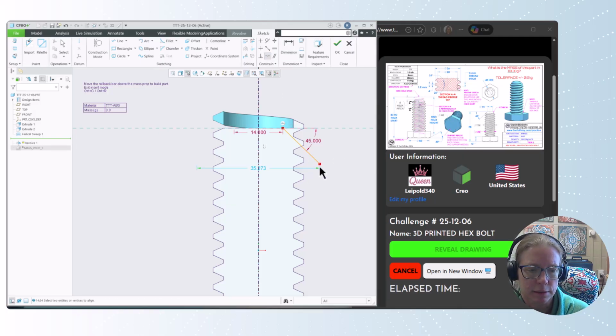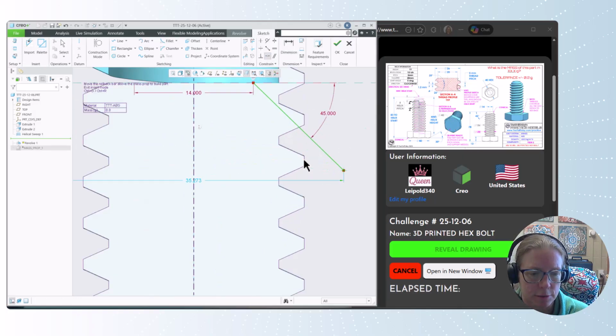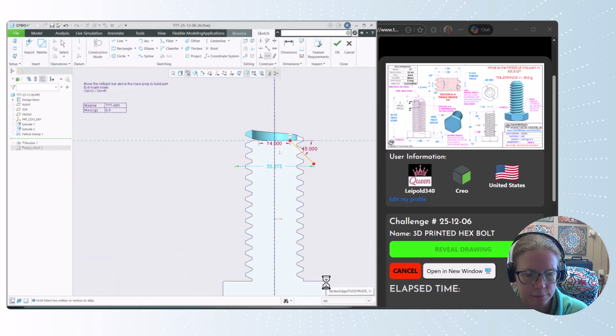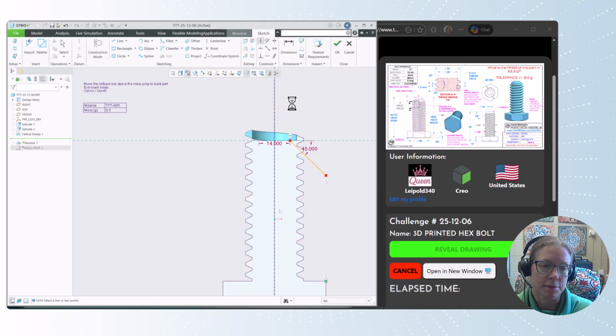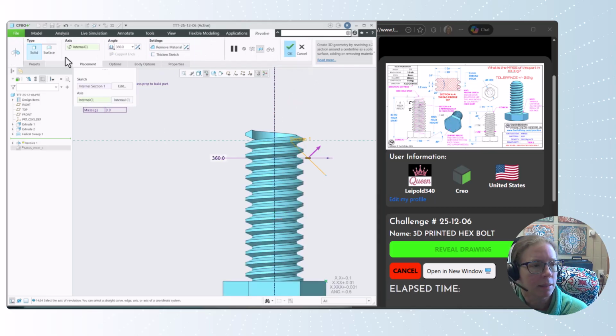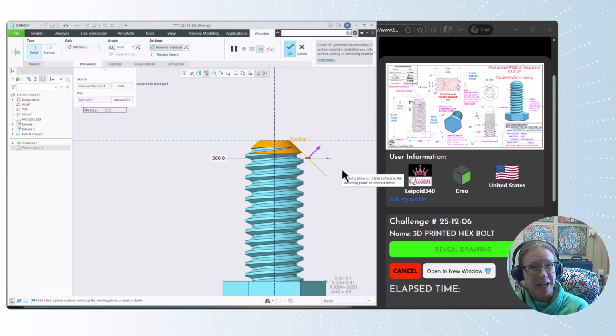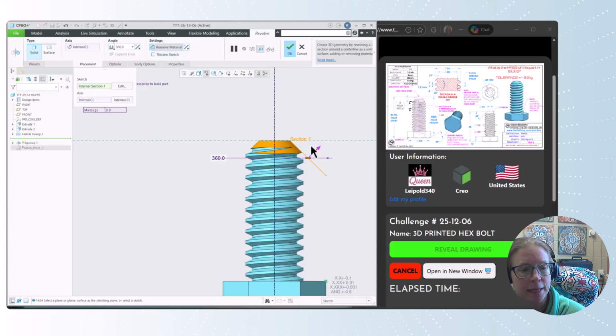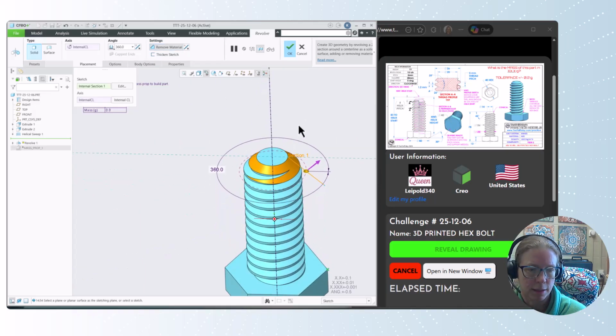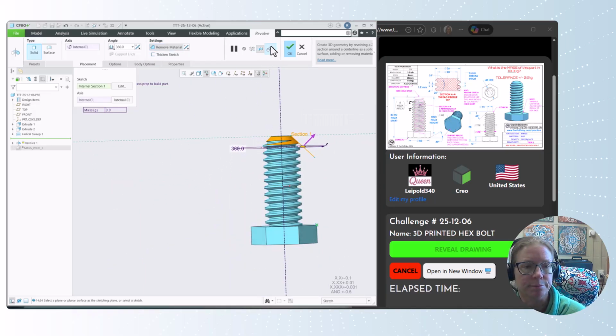And I think I can make this just stick to, you know what? I'm okay leaving the diameter, but if I really don't want it, I can just make it stick to the farthest outside. You'll see that it doesn't really matter. I'm going to leave it as a solid and tell it to remove material. It's an odd looking cut, just being this line with a revolve, but it will work to get that geometry that we need at the top.